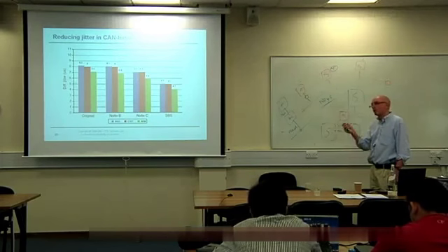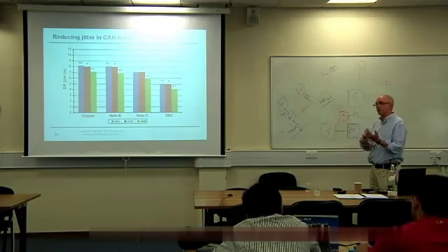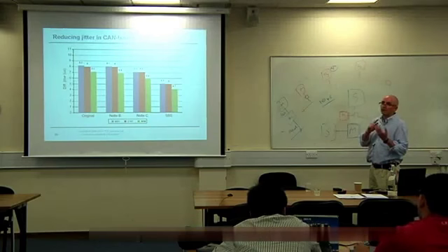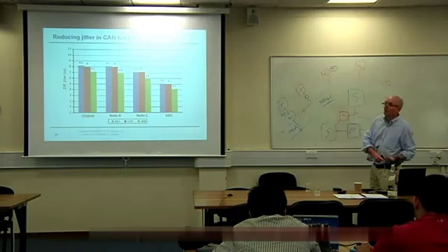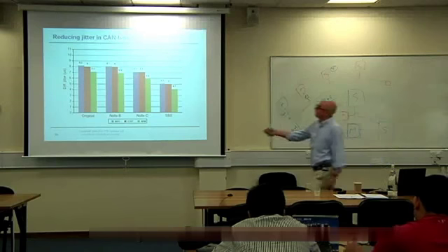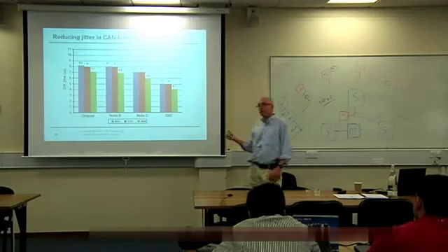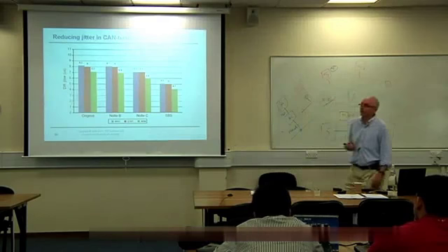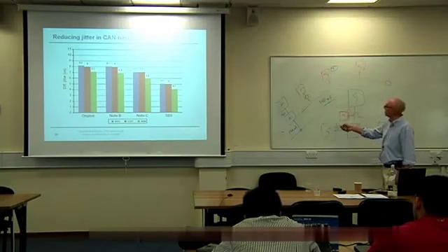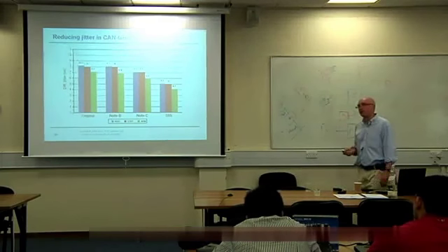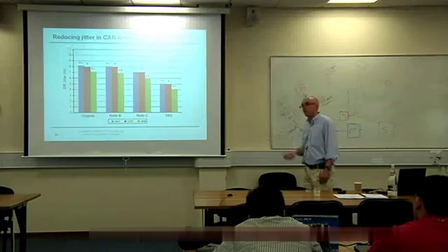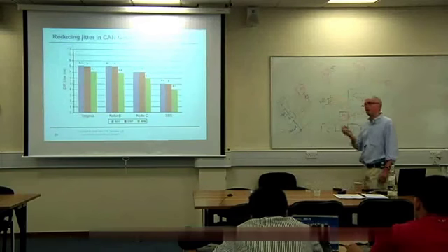The point really is it's a bit like the RTOS things that we were talking about over coffee. You shouldn't be using an RTOS in your system if you don't understand how it works. If you're going to use anything like this in your system, you need to understand the implications of it. So if you have tight timing constraints, you need to be aware of what the network is doing and what it might be doing to that.